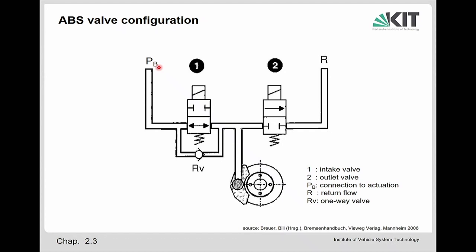So also for safety reasons, the driver would like to stop this emergency braking, so he will release the brake pedal. And release of the brake pedal always needs to reduce the brake pressure on the wheel brake. And if this is closed here, and here the pressure would be released, nothing would happen. So the high pressure would still be here, and we would still continue emergency braking.